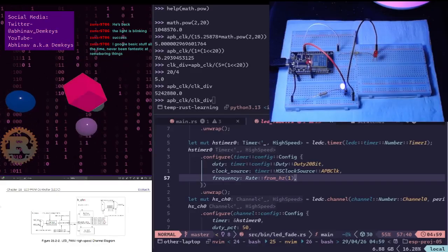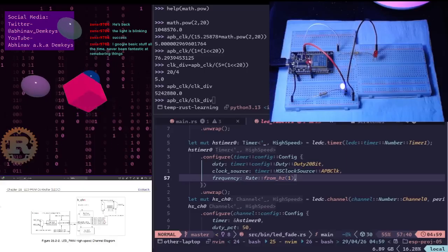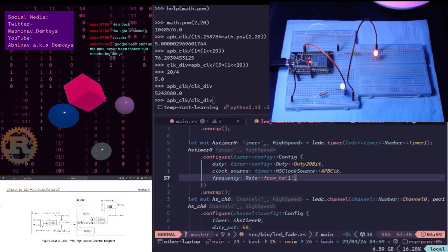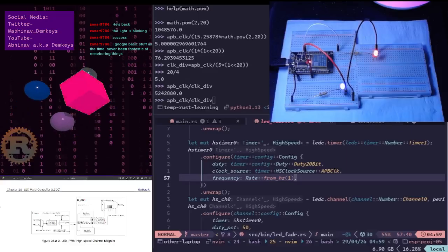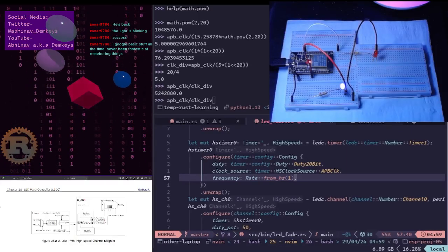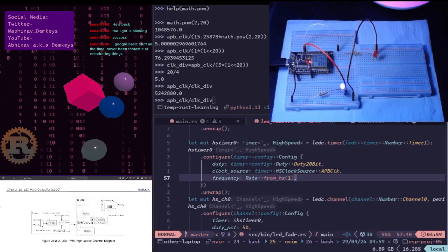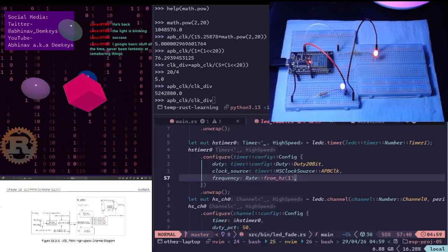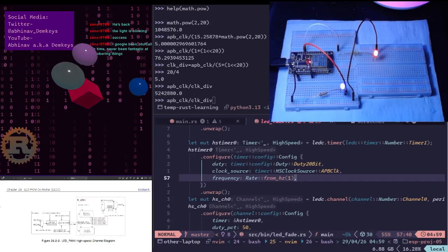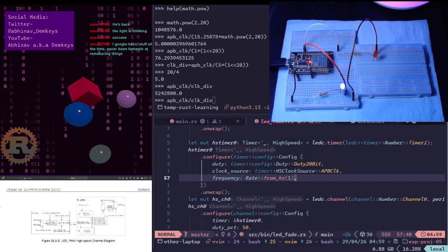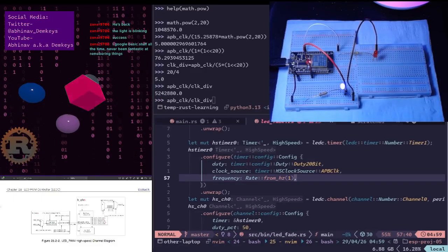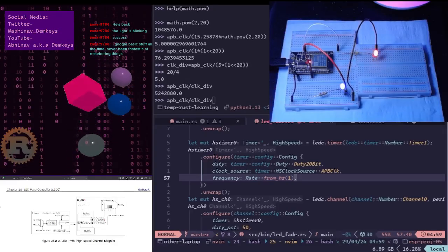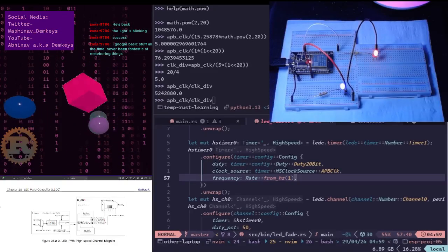The trigger. When the internal counter is equal to the division factor, the hardware generates a single cycle pulse, or a tick. This pulse acts as the enable signal for the actual PWM counter, the one that determines your duty cycle.